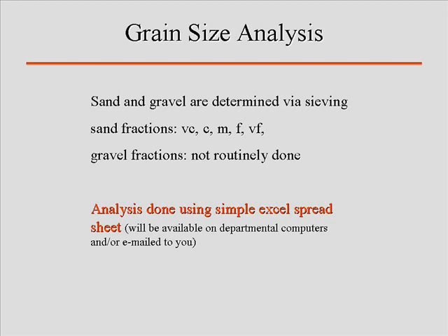If you're wondering, why are we doing the pipette and sieve method? Because it does seem like it's got a lot of work. There's two benefits, I think, to pipette and sieve that the hydrometer method does not really allow you. Number one, the hydrometer method requires you to come in and be here virtually on call for 24 hours. You have to start your samples with pipette and sieve, and then 6 hours later you're doing the second run, but then you're done. And within that interval of time, you can do other things.